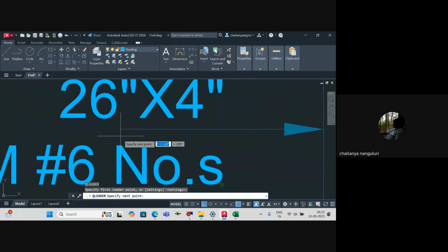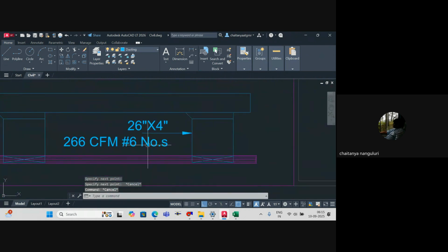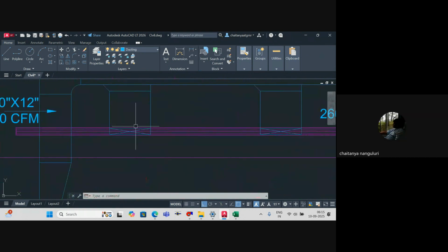For collars, we'll not do it at all, because the distance is too small. Previously, I got 1 is to 40, which I really didn't like. That's the reason I made it into three collars. Of course, even that you can provide. For collars, we have a rule that it shouldn't be greater than 1.5 meters. Moreover, we'll have a grill or collar damper inserted into it so that it will not bend.